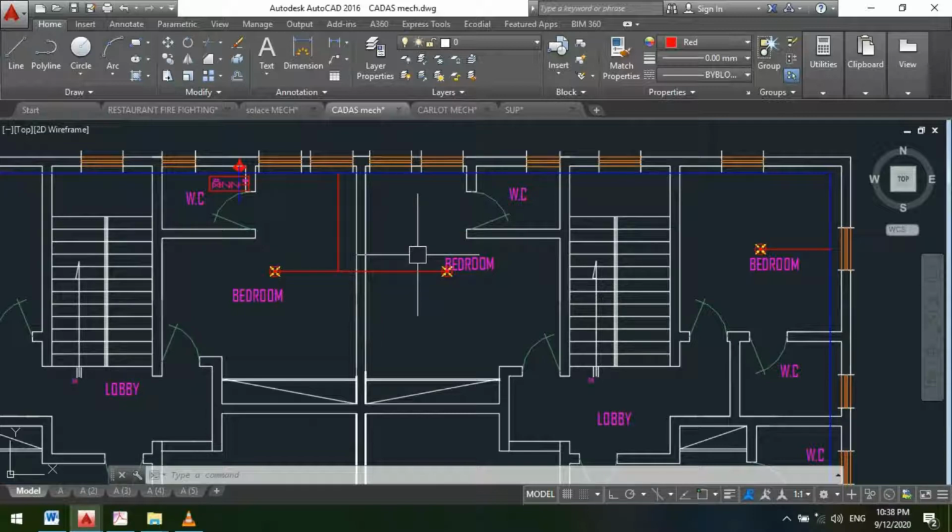Moreover, NFPA also specified that for each project, the maximum area a zone can accommodate is 2,400 square meters, especially for life safety systems, and in the case of property-based buildings, the maximum is 6,000 square meters. Other than that, we will be required to create another zone in a building.